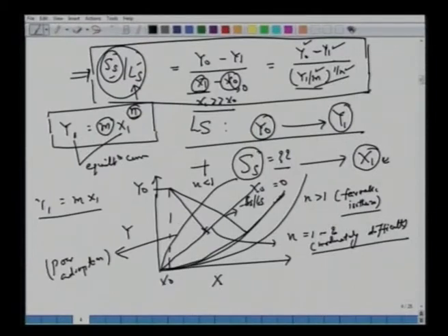It's very difficult to remove from the solvent phase, because look at the slope here, it keeps on decreasing. In this case, of course, you will have the slope like this. So we have three cases depending upon the type of isotherm, y versus x: n greater than 1, n equal to 1, n less than 1. N greater than 1 is a favorable isotherm. Look at the slope, here also it is minus Ss by Ls, here also minus Ss by Ls. For the same amount of Ls, you can see from here you require a very large amount of solids.